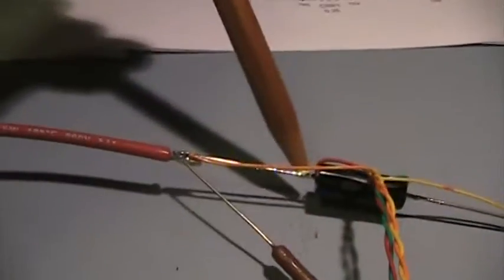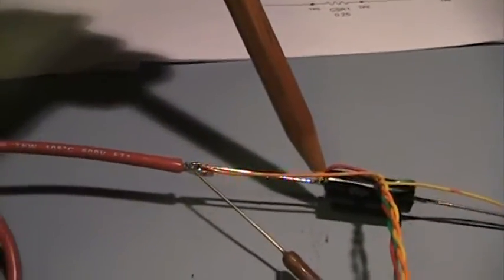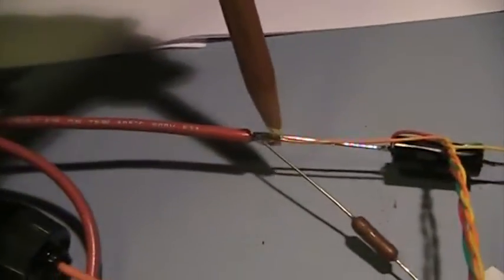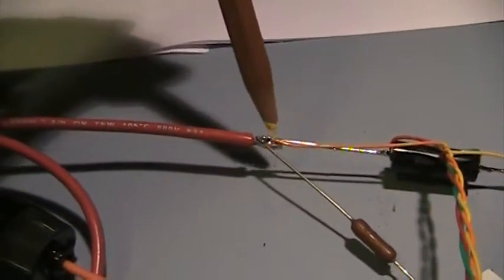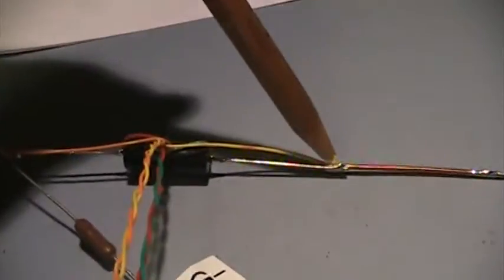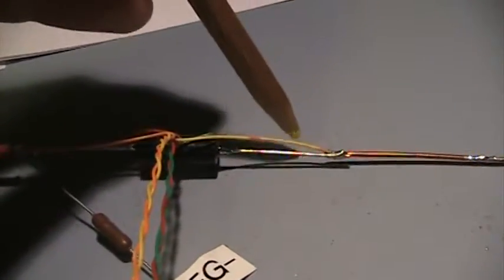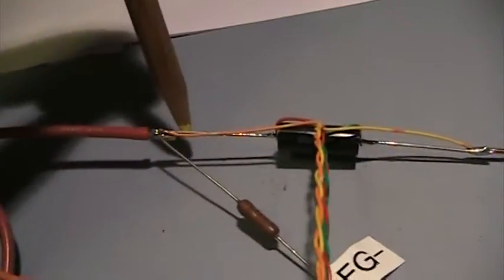One pair, the green and red, is soldered right tight to the body of the CSR, and the orange and yellow pair is about 1 inch or so on either side of the resistor to emulate our negative mean battery measurement.